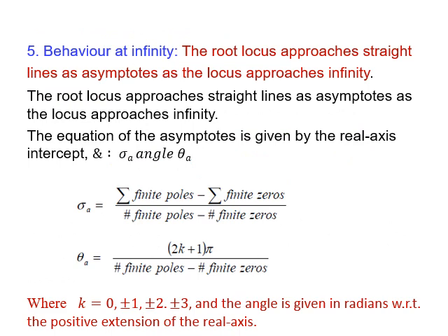Now, if I want to start taking the lines toward infinity, let's consider the 3 elements mentioned earlier. Let's say -1, -2, -3. Let us start drawing the root locus. To start, you'll find there is one line here and one line here. It's very clear that this pole is supposed to go to 0, and this pole is supposed to go to 0. There are no zeros on the S-plane.